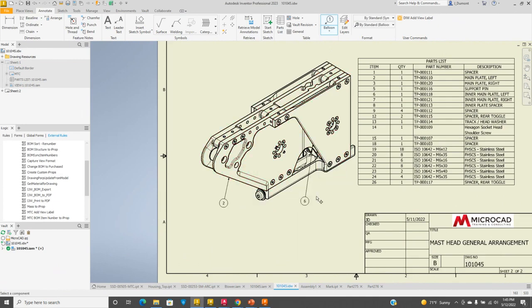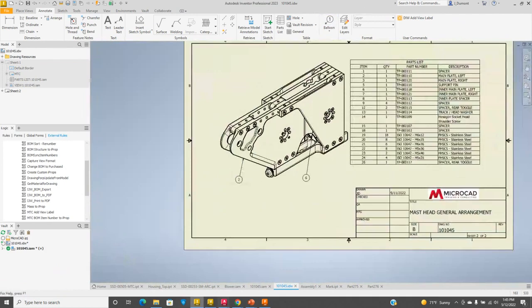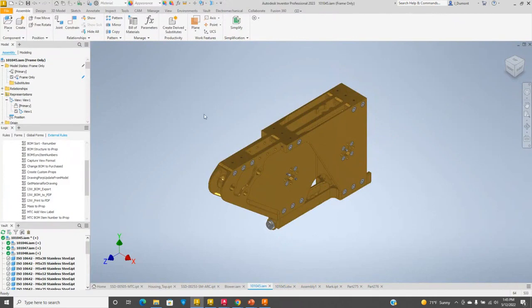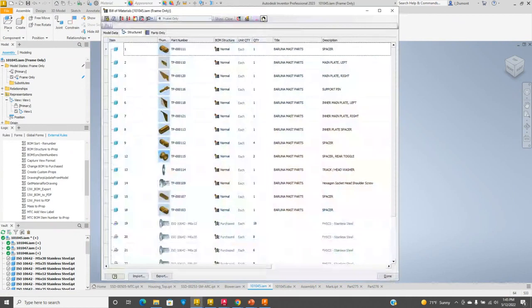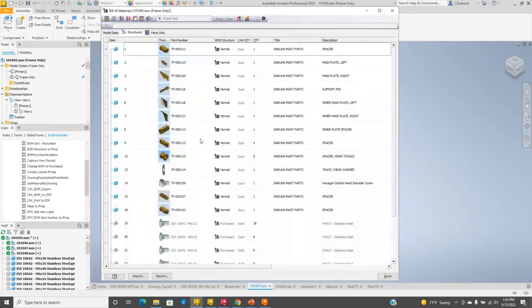And that looks good. You have to be careful because if it's doing the resequencing, that could be a different item number when you do your different model states, when you switch in. If there's a big gap between where they are in the actual list, if I'm shutting a lot of components off, it could vary that. You just have to watch your renumbering because basically what it's doing is I've got 26 items here.